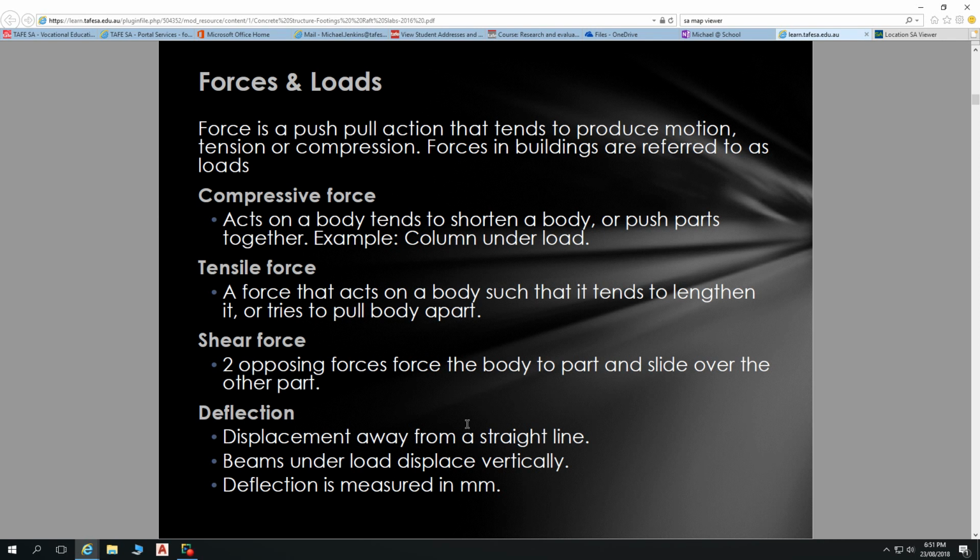Another important aspect to think about when we're thinking about deflection is the deflection of roof trusses as well. I'll just quickly talk about that. With your standard pitched roof, where we've got rafters, underpurlins, etc., all these elements work together to hold those rafters up.